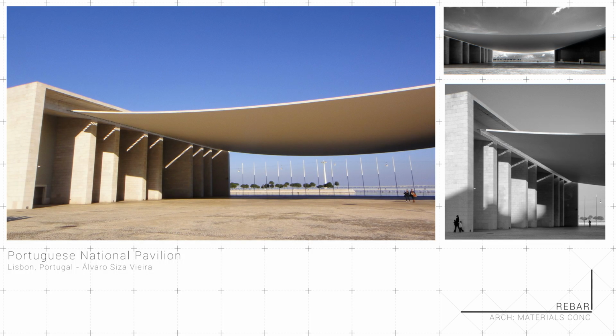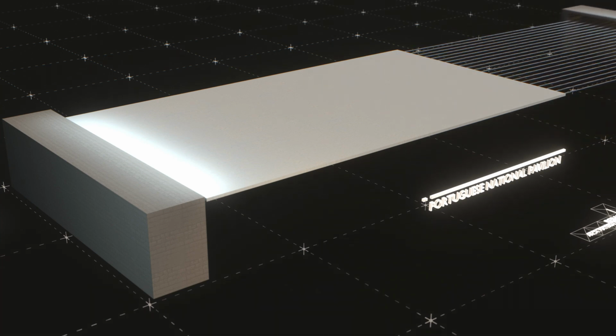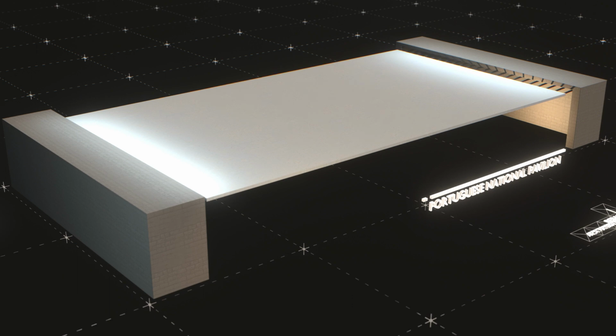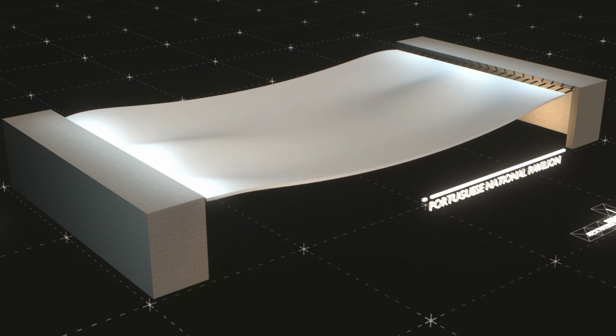A more outwardly visual representation of the system is artistically portrayed with the Portuguese National Pavilion in Lisbon, Portugal. The space frames an impressive view beneath a sweeping concrete one-way slab. It basically looks like a tarp or some sort of fabric, but it's solid concrete. A magic trick in materials achieved through the embedded post-tensioned cables hung between two concrete structures. The internal cables aren't all the way taut and thus have a swoop in how they're hung. Aesthetic design reflects the structural conditions within.